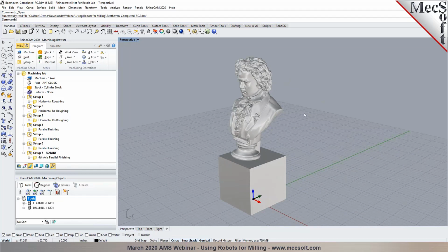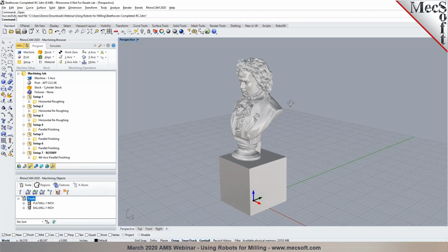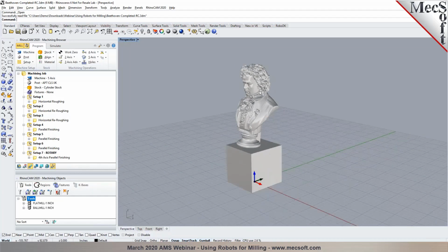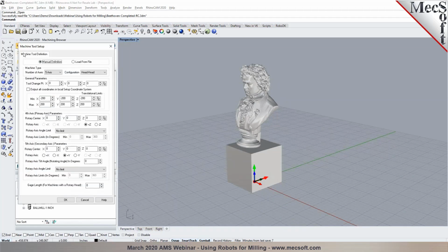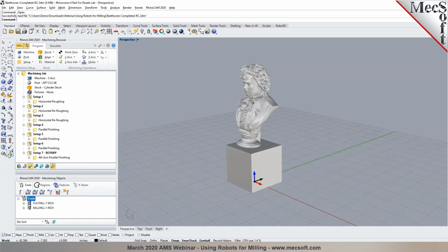So we would like to show you how this can be done very efficiently using index 5-axis, also known as 3+2 machining, where you lock the coordinate system for machining to any given plane, and you can generate toolpaths. The machine setup process is going to be very similar to what we did for the simultaneous 5-axis in here. And then to program from each orientation, we will generate roughing operations and finishing operations from each orientation.